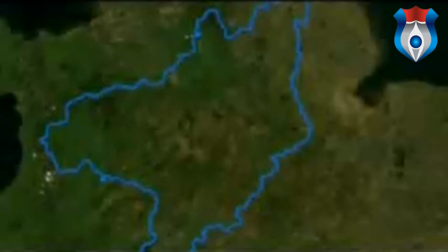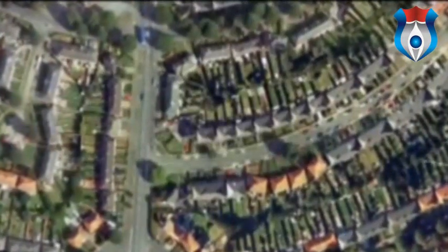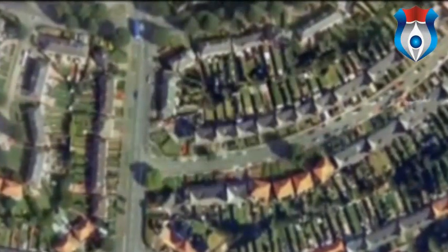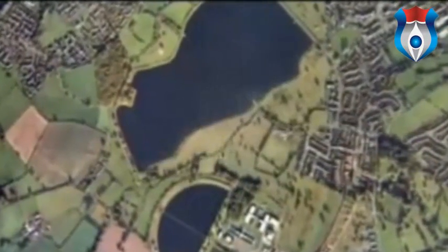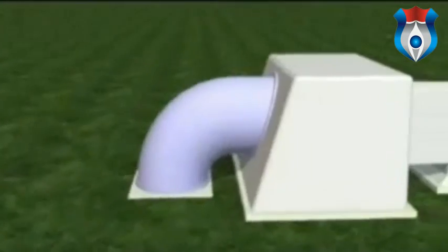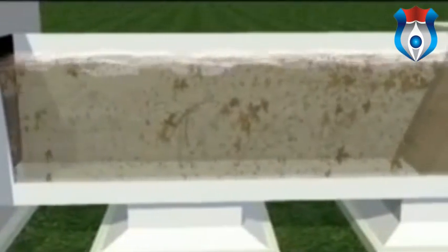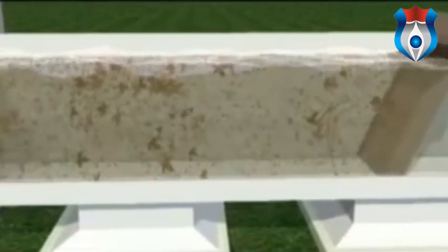This is a very basic overview of the water treatment process. Customers always need water, but rainfall is seasonal and increasingly unpredictable. So we often use storage reservoirs to make sure there's always a supply for treatment. By passing water through mesh screens, we remove sticks, water weeds and other large foreign objects.